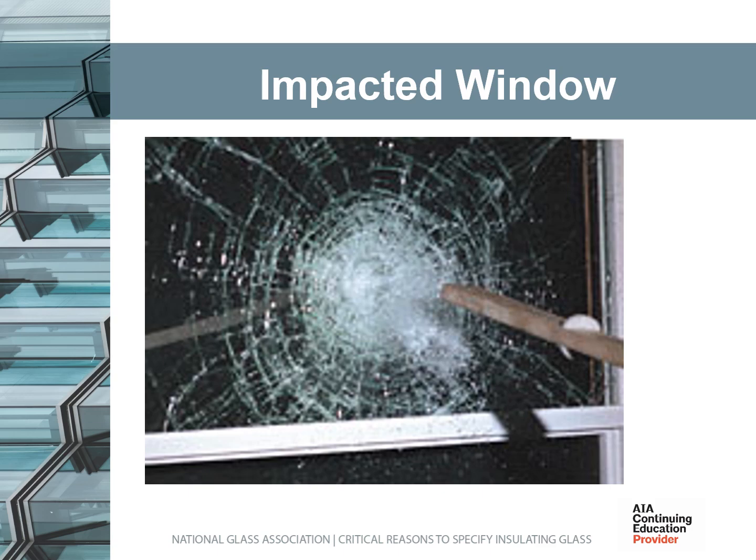Part 2. The cycling portion of the testing is then conducted on the same test window to ensure that a window having withstood impact by the 2x4 can then stand up to rapid increases and decreases in pressure within the building during a hurricane. Within the laboratory setting, this is done by introducing 9,000 cycles of differing pressures to the impacted unit. Common test methods and standards surrounding hurricane testing are State of Florida TAS 201, 202, and 203, ASTM E1886 and E1996, AMA 506, Miami-Dade County testing protocols, etc.